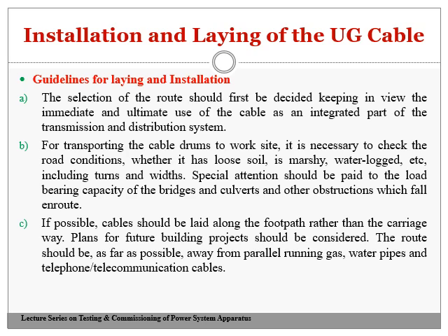I cannot fix a UG cable which can carry only 200 amps if, within 2 days, the load increases, because then the cable burns itself. That's why it is always essential to have the proper cable in the proper path, especially laid in the footpaths rather than the carriageway.